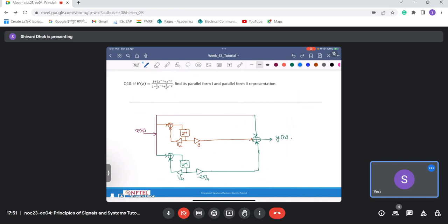Basically, in the entire course, if I look at it, the LTI systems are predominantly used in filters. Any LTI system can be characterized. We can say that any LTI system is a filter, because it will have its own impulse response. It will have its own magnitude and phase response. It will reject and pass some frequency. So any LTI system, we can safely say that it is a filter.